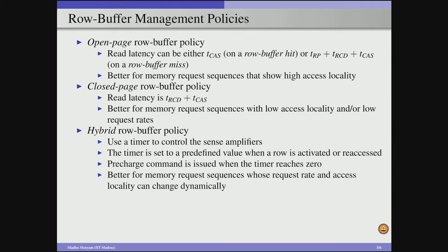So, effectively, rather than closing an open row immediately after a cache, we keep the open row for some amount of time, but we are not going to keep the row indefinitely until there is a row conflict like an open page policy. So, we consider a fixed duration, and we specify this by using a timer associated with our memory controller. The timer decrements its count, and whenever the counter becomes 0, we close the open page, and if there is an access to the open row, the timer resets to the fixed value again.